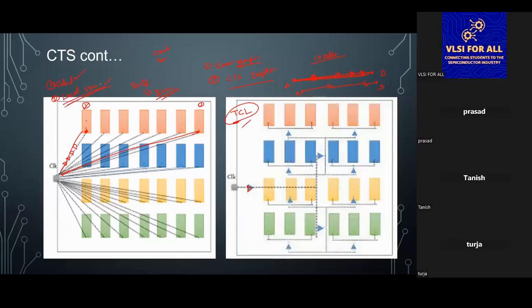Sometimes you will increase the local skew, it is okay, it's fine. You can fix the violation. It won't impact the design, only the path. For example, in the same location here, I need to add some 2 cells here to fix my violation, or I can add 2 cells here to fix my whole violation. So it will do some changes in my skew and insertion delay.